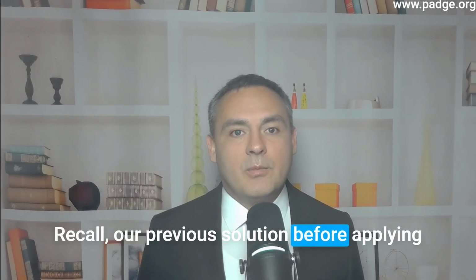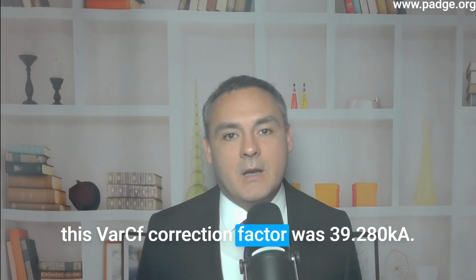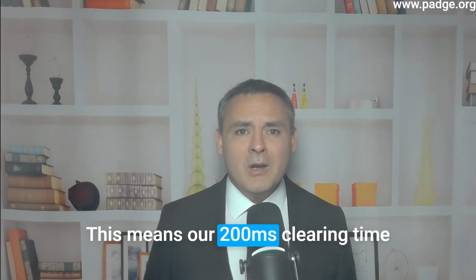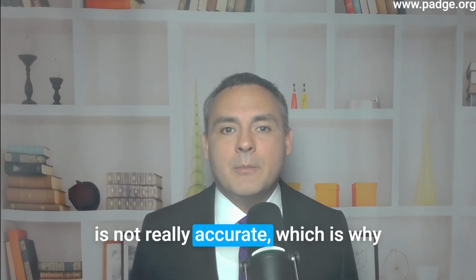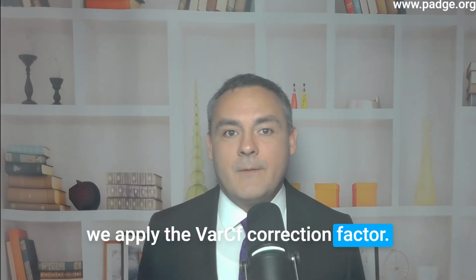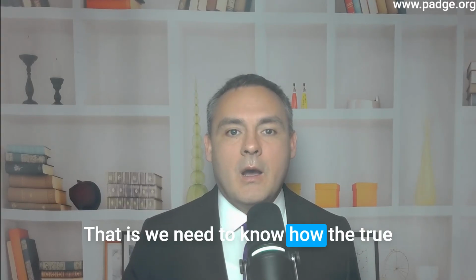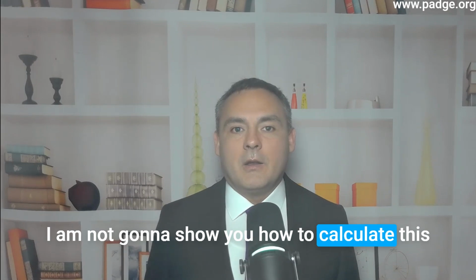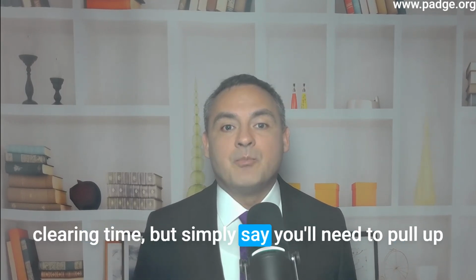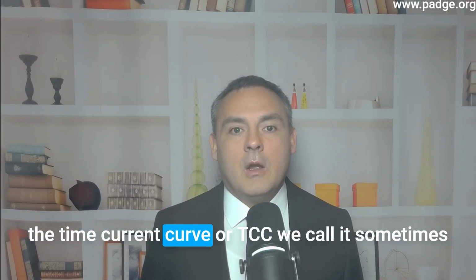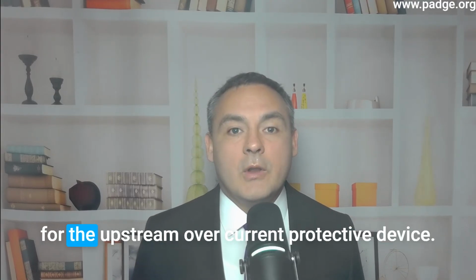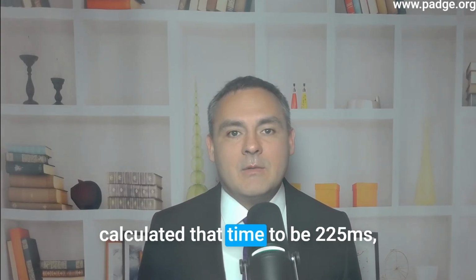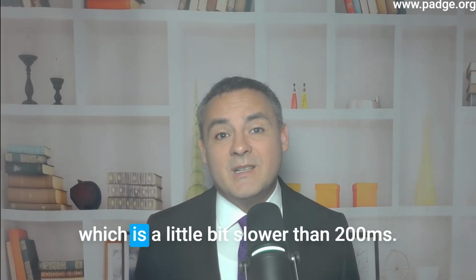Recall, our previous solution before applying this VARCF correction factor was 39.280 kA. This means our 200 millisecond clearing time is not really accurate, which is why we apply the VARCF correction factor. That is, we need to know how the true arcing current affects clearing time. I am not going to show you how to calculate this clearing time, but simply say you'll need to pull up the time current curve, or TCC we call it sometimes, for the upstream overcurrent protective device. I did that for our example and calculated that time to be 225 milliseconds, which is a little bit slower